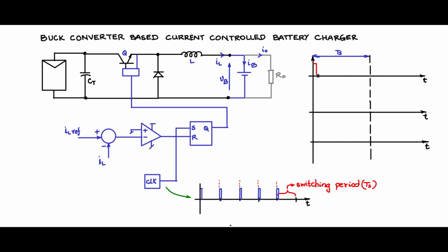So at the start of the cycle, you have a small duty cycle pulse, and that is this clock pulse, and it happens at every starting of the period. Now the moment this clock pulse is given, it sets this SR latch. Q is high. Moment Q is high, there is base drive for the BJT or gate drive for the MOSFET, and this is on, and VT gets connected and the inductor is charging up. The inductor current is growing.